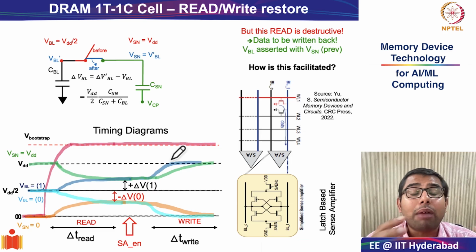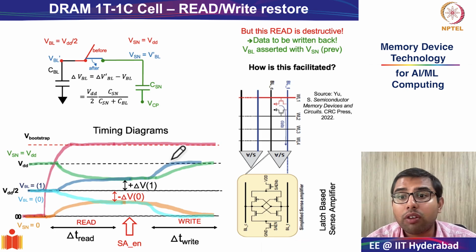Also, the DRAM subsystem architecture, which was this inverted hierarchy of starting from the array, going up till bank, and then chip, then DIMM and channel, and so on, which helped us gain a lot of parallelism and try to somehow mitigate the memory wall, which is the big difference in the performance of the CPU versus that of the main memory subsystem.